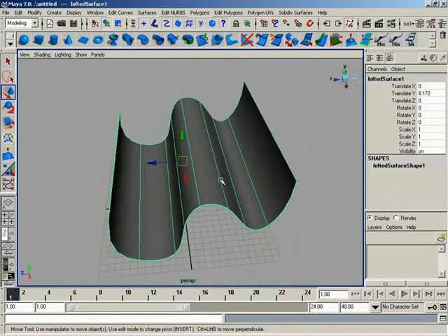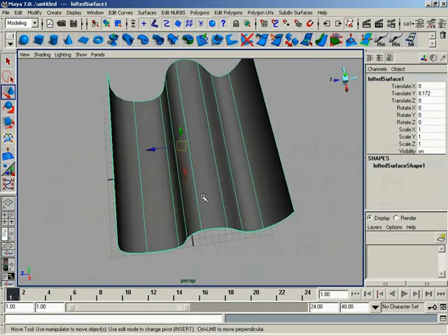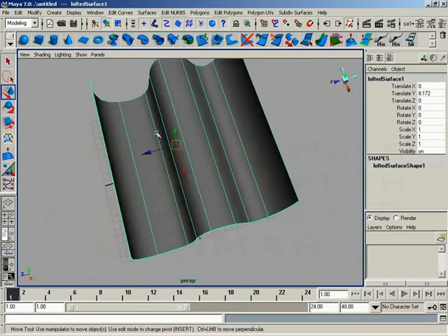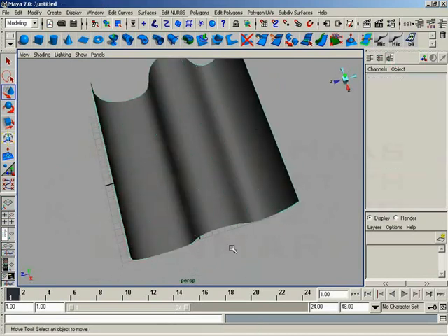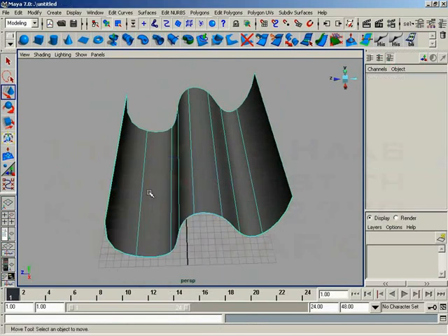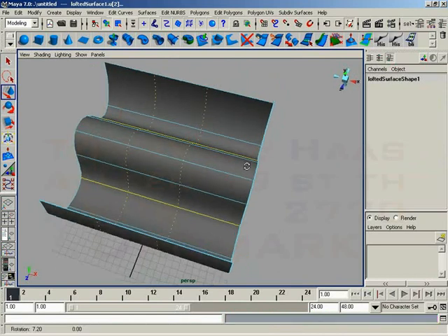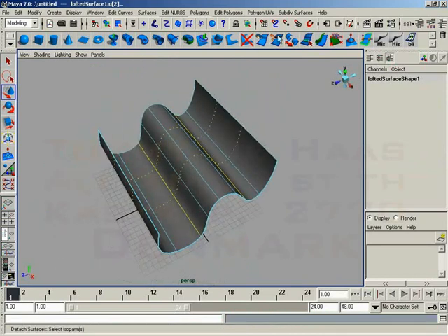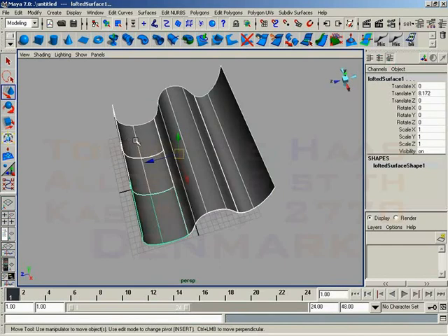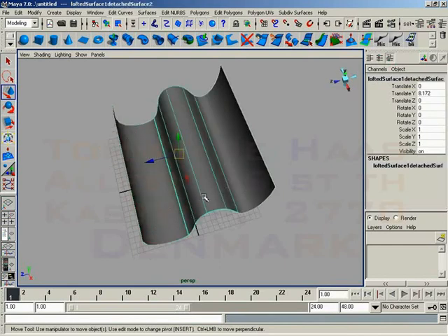For example, if I want to cut this NURBS surface up, kind of like a tic-tac-toe board, cut it this way and then this way twice as well, watch what happens. If I select a couple of isoparms here, and we'll grab an isoparm here and an isoparm here. If I try to cut this up, watch what happens really closely. Boom. We have 1, 2, 3, and then 1 and 2. Now, why did it do this?